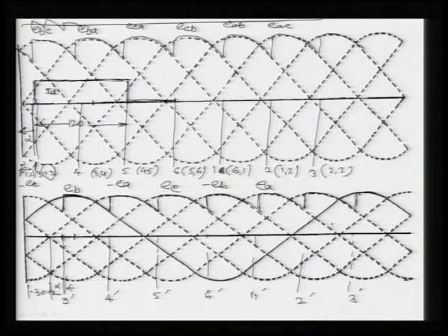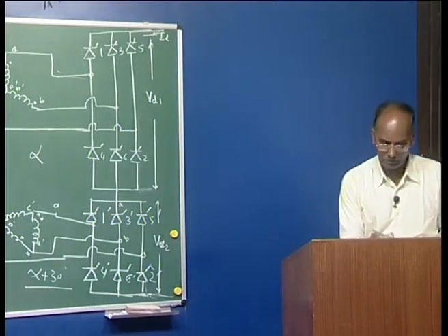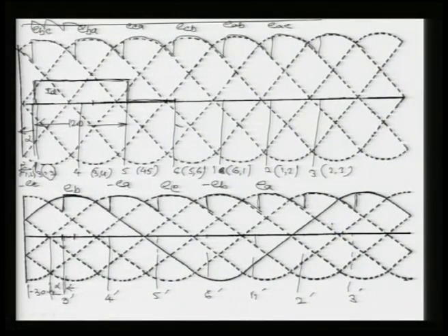Up to the 6. Now, you see once 6 is getting a pulse, the current in this phase is going to be on the negative side, coming from below, and it will again go for 120 degrees, because 6 is there. So, again this value is your ID here, and it goes for 120 degrees.